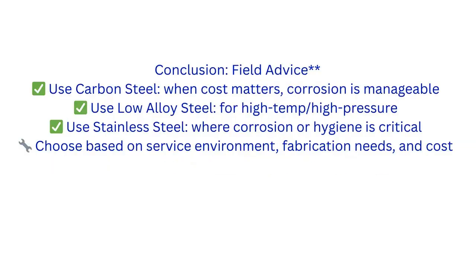To conclude, use carbon steel when cost is the priority and corrosion is manageable. Use low alloy steel when high temperature and pressure are involved. Use stainless steel when corrosion, hygiene, or longevity matters, such as offshore, pharma, and chemical service.